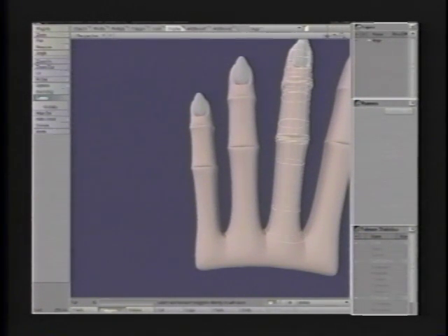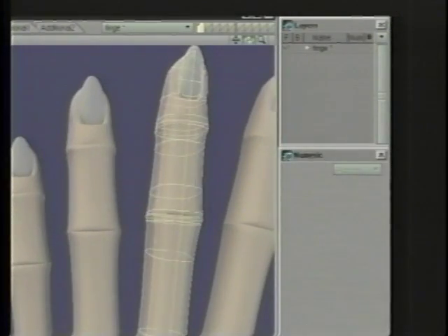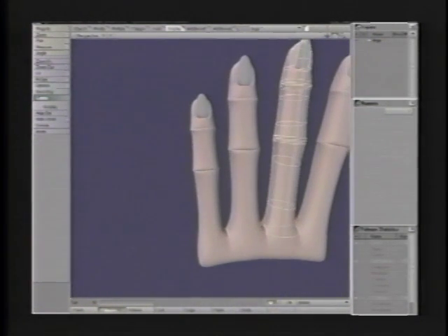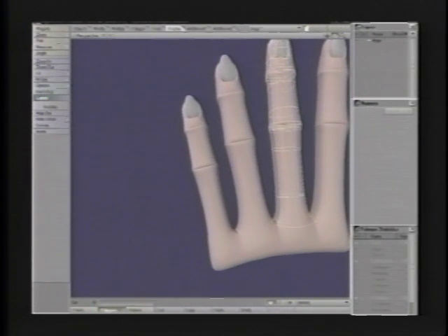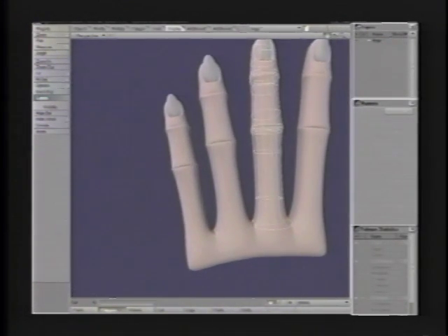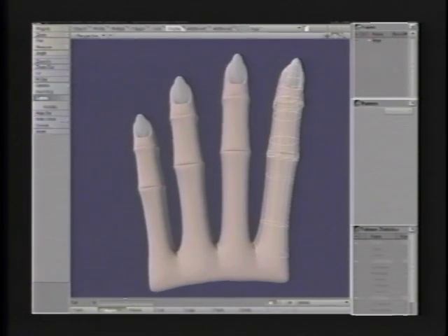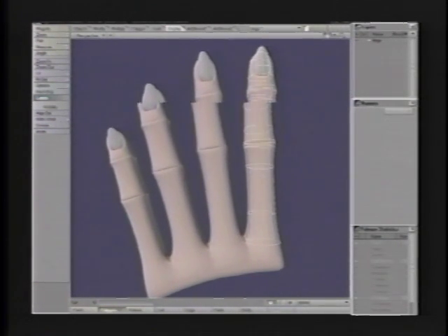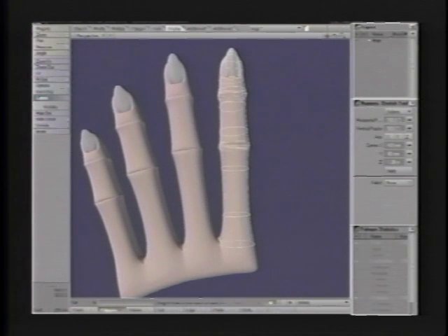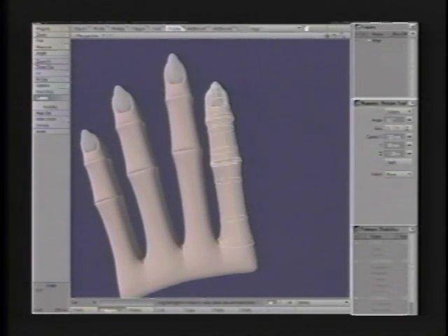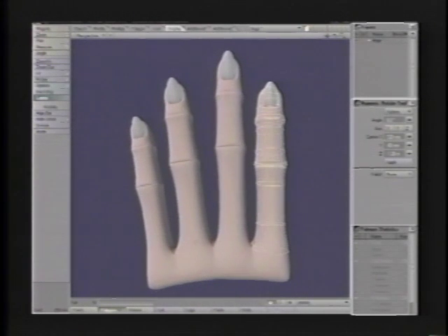And next finger. Again, using my select connected expansion. And here's an interesting thing about the view widget I should point out. If I use my left mouse key and I rotate, see it rotates on these axes this way. If I use my right mouse key, because you'll notice sometimes it gets a little off, it adjusts the other angle. So that gives me a real good way to adjust that quickly. Then I can pan this over, make sure that's right there. Since this is the largest finger, I don't need to edit it anyway, so we'll just skip that. And move over here to our index finger. And once again, using my right mouse key, just roll that right over, center it up, and stretch it down and in just a little bit. And this one should be slightly larger than the pinky. There we go. Okay, so there's the beginnings of the hand.